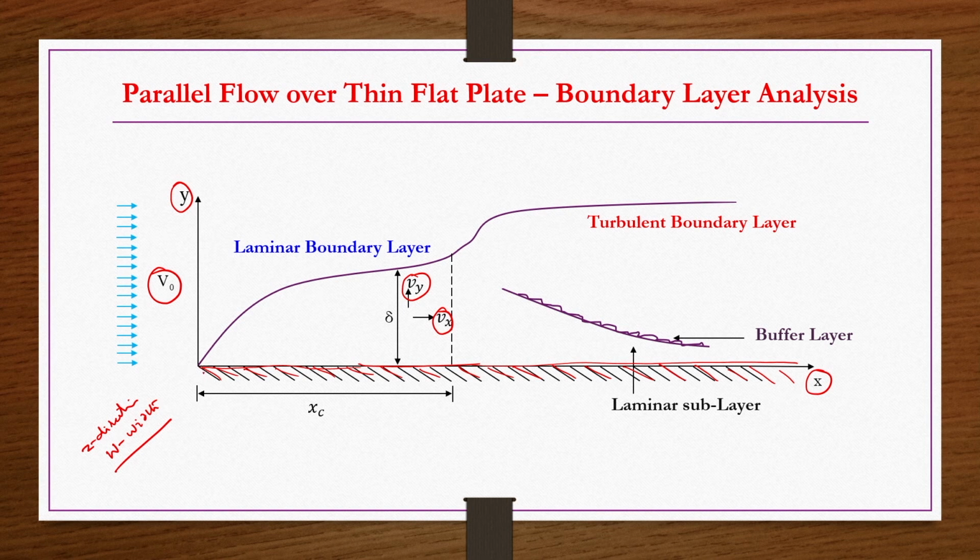The fluid elements experience retardation only for an infinitesimally small, negligible time at the leading edge. But as you move further in the flow direction along the solid surface beyond the leading edge, the fluid elements experience more and more retardation, so gradually the flow slows down.